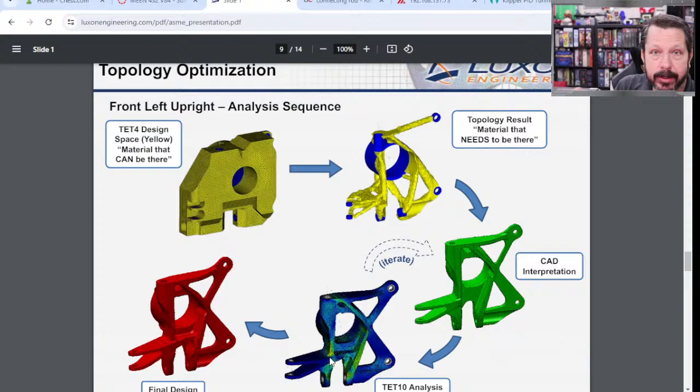There's kind of a high stress right in this corner, right in this fillet here, it looks like, but we don't have a sense of how high that stress is. Usually in these things, the red is something that is giving you a factor of safety lower than 1, but you could actually make it give any range of numbers. So maybe they have a little concern right there.